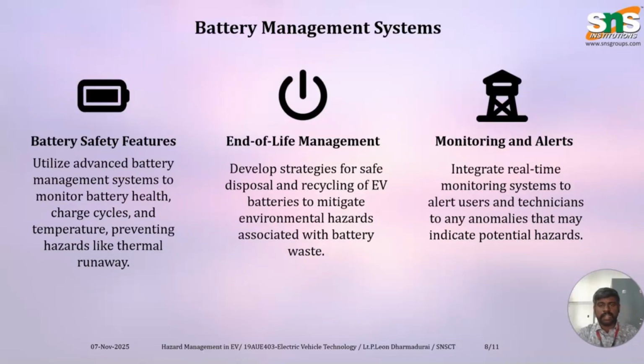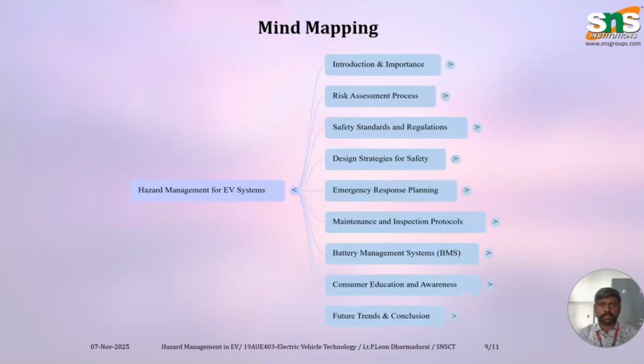Some of the technical things include the battery management system, BMS. It continuously monitors the battery health and the battery charging state, and it also measures the temperature. With the help of this, we can monitor the battery health and act accordingly on its input, so that we can prevent big problems in EVs.